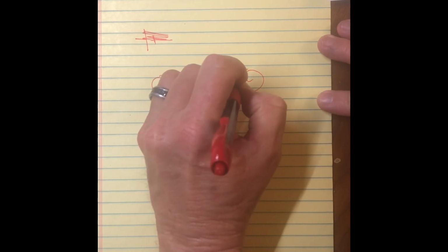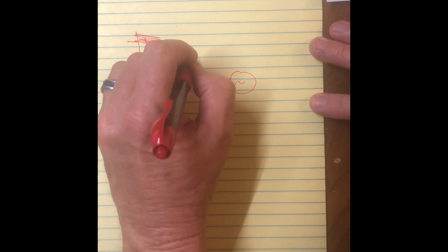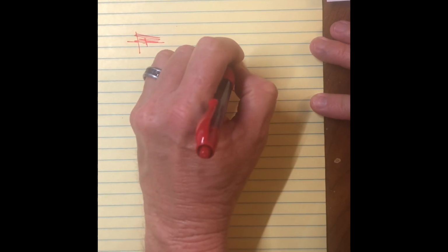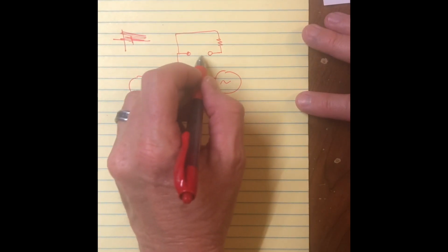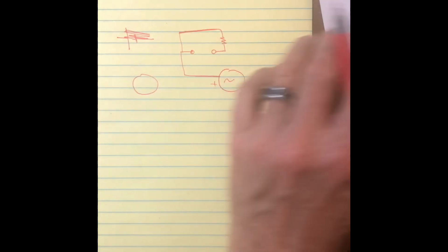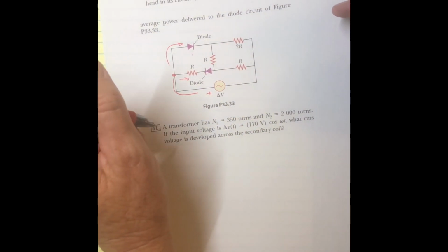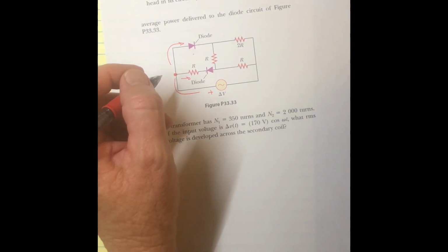So if you had a DC circuit here, where this was positive. Well, maybe I shouldn't put DC, that might confuse you. We'll do it here, so I had my AC. When this side is positive, it's like this branch right here has been eliminated. That is an open circuit. It blocks the current. And this branch up at the top is just a straight wire. Now, that's not completely true. Diodes do need a little bit of energy to turn on, so they take their energy from the circuit. But for simplicity's sake, I'll just say it's like a wire.